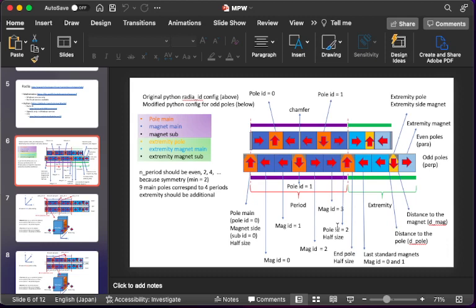However, Radia has a mirror function, so you have to model just half of the magnet, and the model mirrors the other side in x, y and z directions, so the calculation cost will be small.